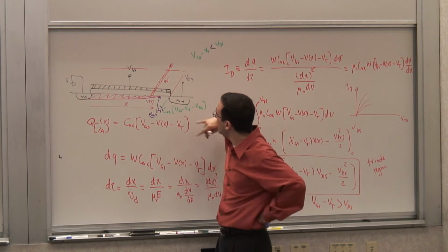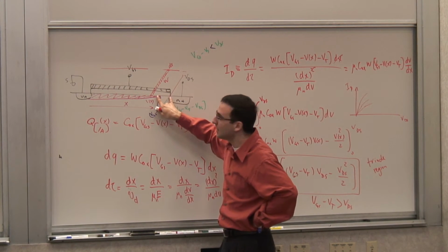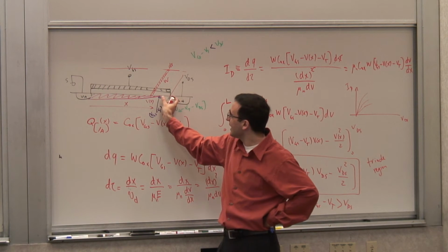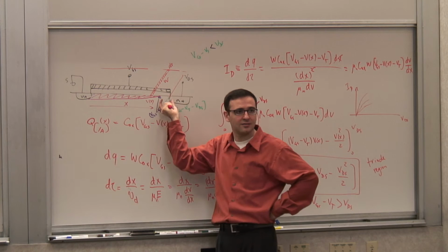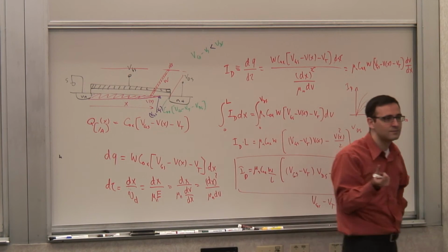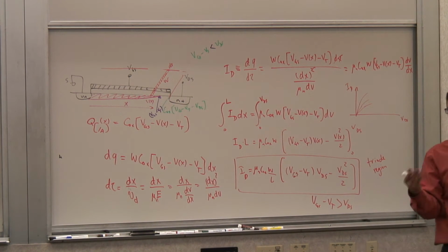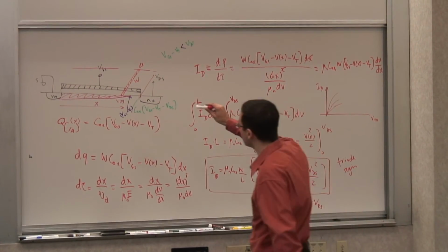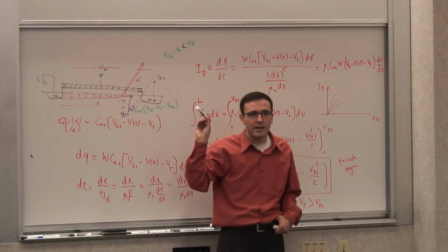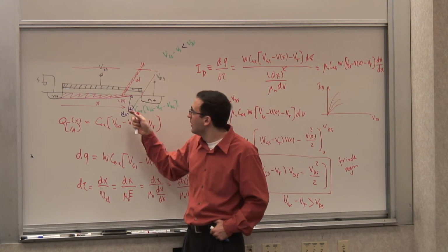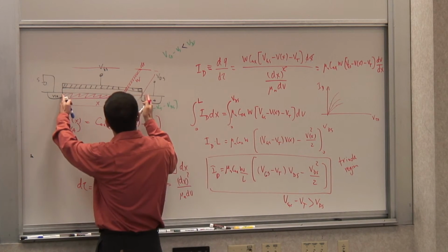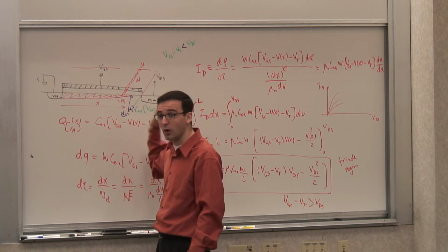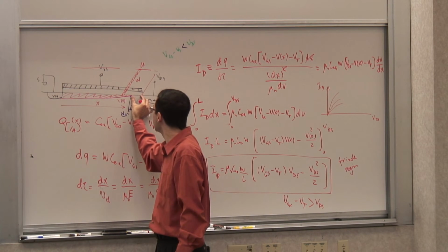Beyond that, VGS minus VT is fixed. Even if I apply a very large VDS, this point goes a little bit farther out, changes a little bit, and most of the electric field actually falls across here. This is the interesting thing to remember about the MOSFET, because in a lot of analog design we will be dealing with this pinch-off region of operation. Although you have a relatively large channel in this case, most of the voltage you apply to the VDS drops across this small region.